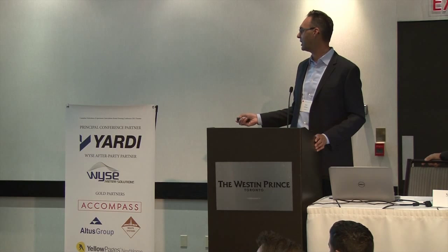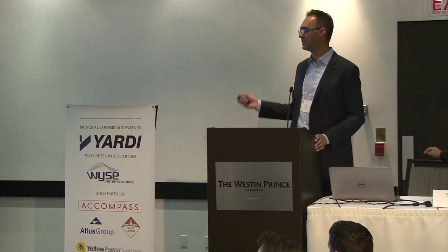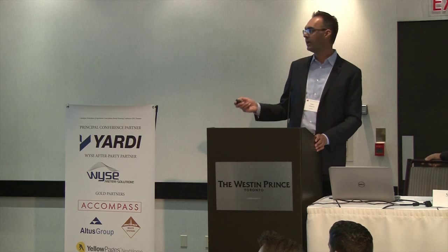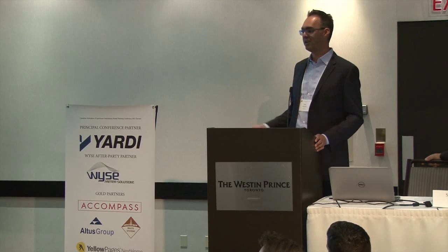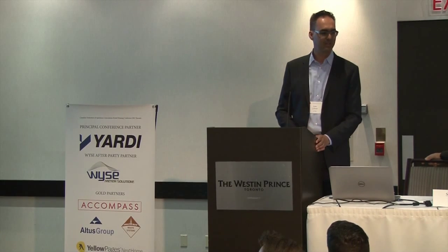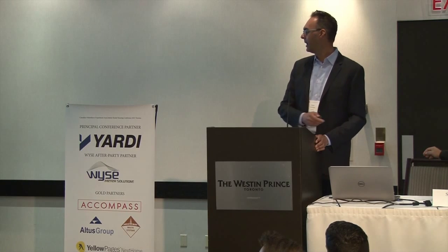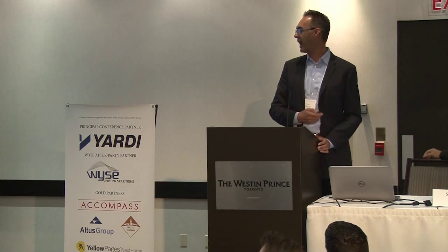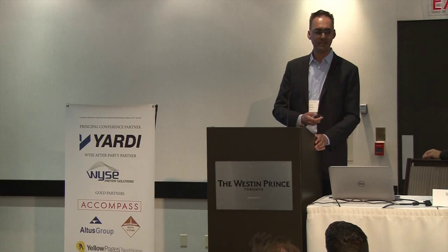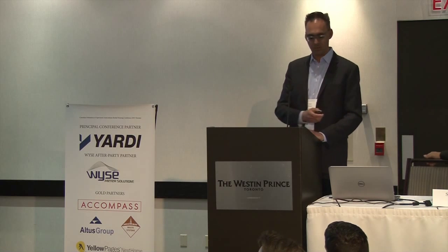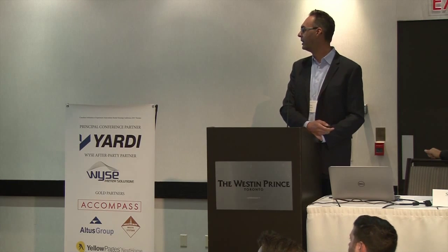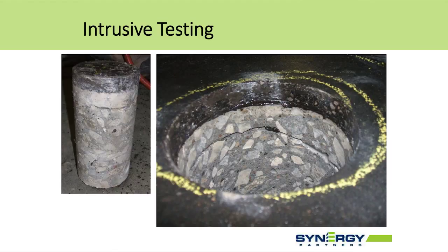And there's a great little study that was done by Building Science Labs. It talks about the effectiveness of drip edges, and even, believe it or not, there are actually different performance based on a different profiling of a drip edge. I'd be happy just to see any drip edge, but you can actually get better performance depending on how you design it. And so think about doing a walk around your properties, after a rainfall, during a rainfall, and see how is water hitting the walls, how is it getting kicked away, where is it going, what's going on. It's really powerful. Intrusive testing is going to be a must.